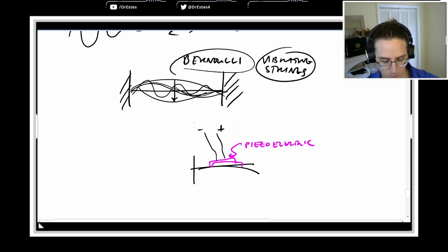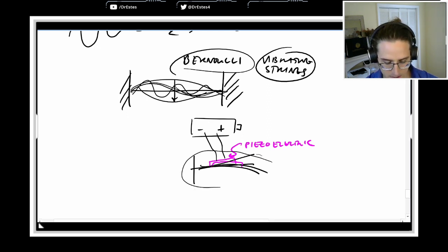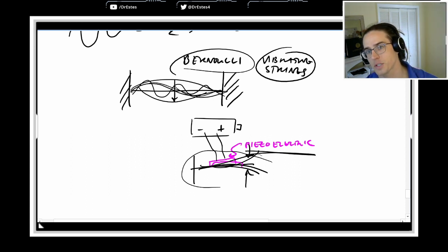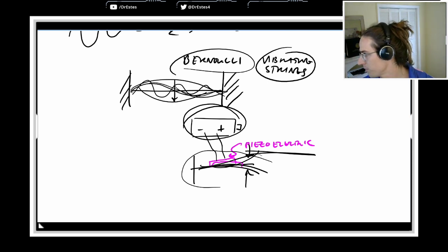And think about it, what if you could store this on a battery? So when you build an energy harvesting structure, you want this thing to vibrate like crazy and deform this piezoelectric material as much as possible so that you store as much energy on this battery. So it's very interesting. For structural things, you want to avoid amplification. For energy harvesting tasks, you want to maximize it, you want to exploit it so that you can get as much energy as possible.